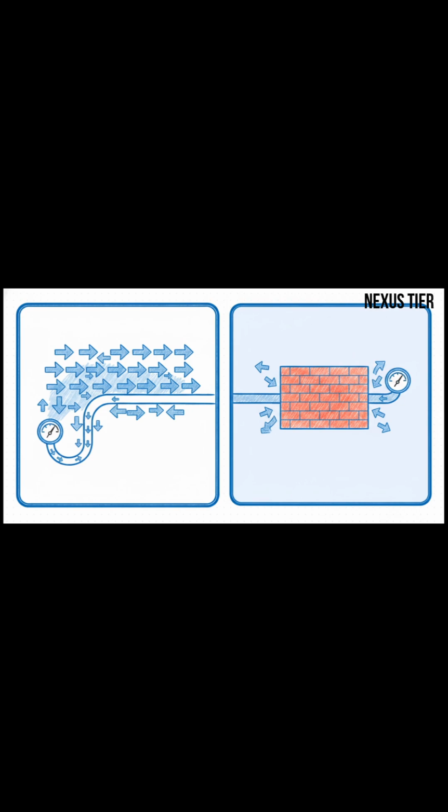On the flip side, to build a voltmeter, we add a very high resistance in series. This actually blocks the current from entering the meter, which allows it to simply measure the potential drop across 2 points without draining the system.